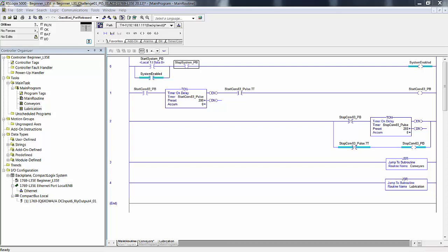Obviously you can see the advantage of retroreflective in that the photo eye, which has a transmitter receiver, has a cable on it, and it electrically has to be routed back to the controller, whereas the reflector is just a physical object attached at the right point, and you have a bracket so it's adjustable so you can move the reflector to the position that you want.